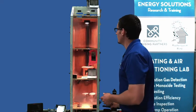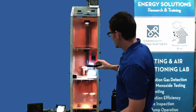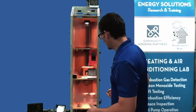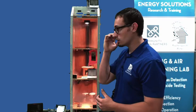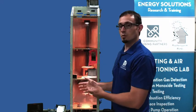Now we've even got fog occurring up top. Man. So, we might do this. We might have caused this issue by air sealing. So we go into the building, we seal it high and low. We did what we were supposed to do to control convection like we talked about, but we didn't pay attention to the house as a system. So we're seeing now the ramifications of what we've done.